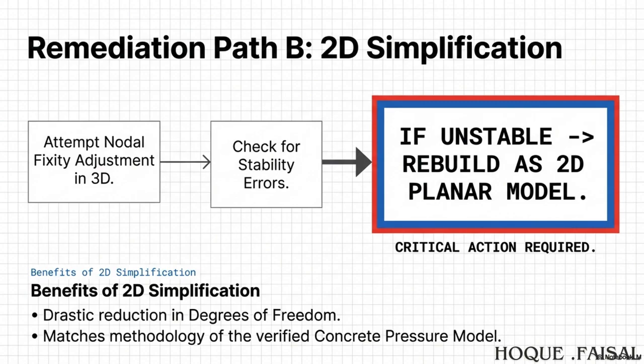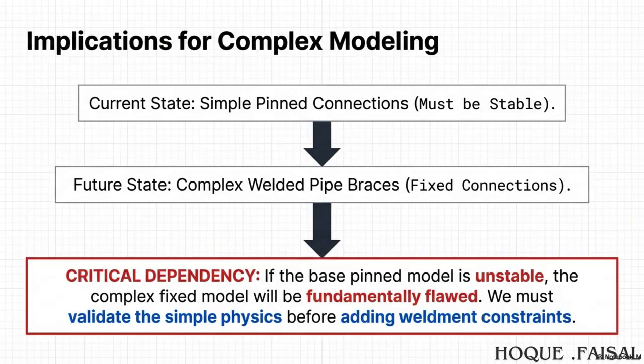Great design. And that right there is the trap, because your reaction should be, wait a minute, that seems physically impossible. Impossible? Why? Steel is really strong. Steel is very strong, but steel is also elastic. It has give. It bends. Everything bends. If you have a 24-foot tall beam, even a braced one, and you hit it with that much force, it's going to deflect. It might not break, but it will definitely move. More than 0.077 inches. A lot more. That number suggests a level of stiffness that implies this thing is carved out of a single, solid block of diamond, not bolted together from construction pipes on a roadside.